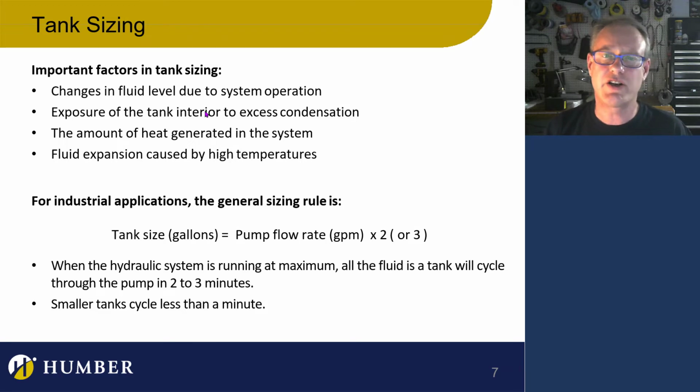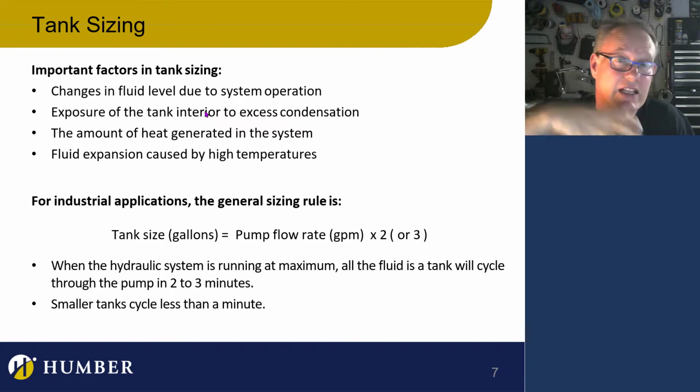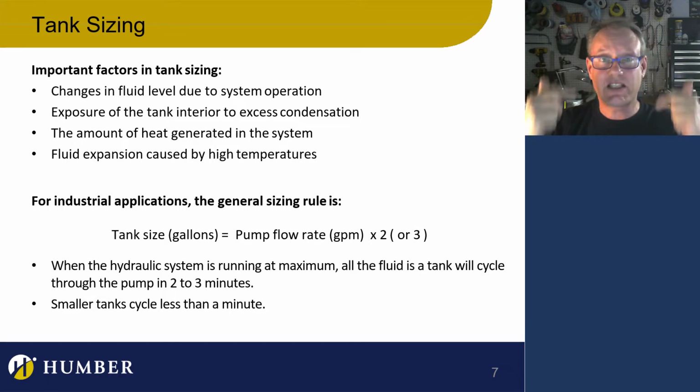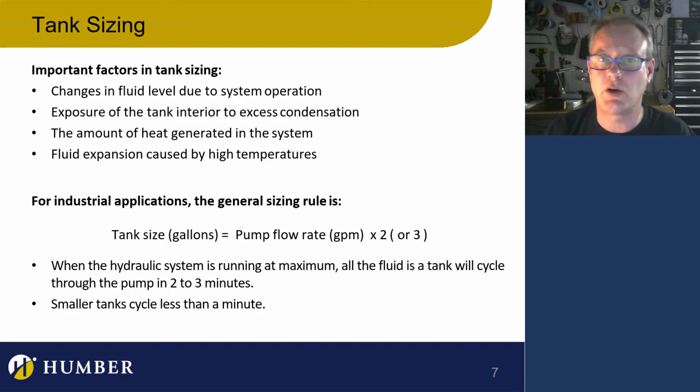So you have to make sure your tank is large enough to accommodate all of those cylinders fully extending and taking up all of that fluid, and the fluid level is still high enough that the suction line is well below the fluid level. So it's important to be able to size a tank. There's a sizing method for this, but we'll go on.